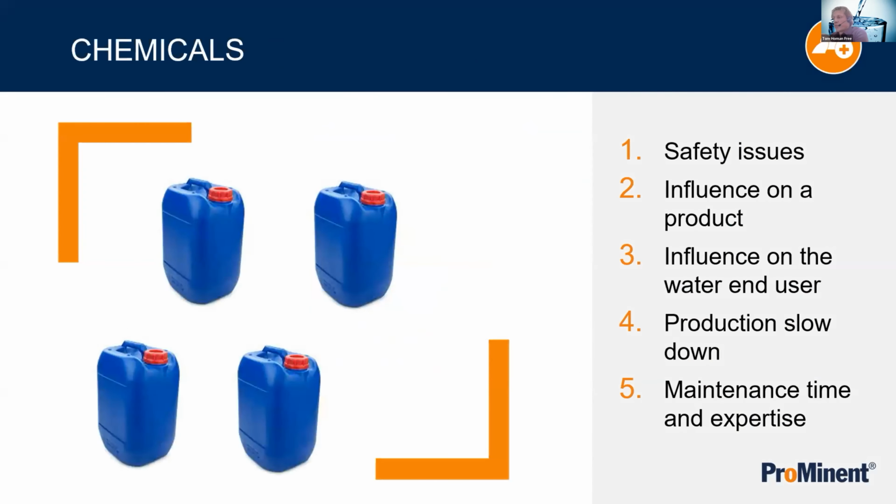And then, of course, we have a wide range of other chemicals. Hydrogen peroxide, for instance, is almost ideal. It dissolves in water and oxygen. We have some residual effect, especially in pipe works, closed-off pipe works. But if we have a look at costs compared to chlorine, for instance, then we can look at a factor 4 or 5 more expensive on your operational side. Peracetic acid requires high concentration and heat. Plus, we have corrosion issues.